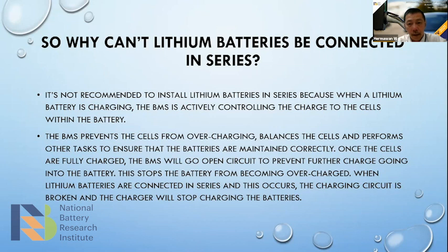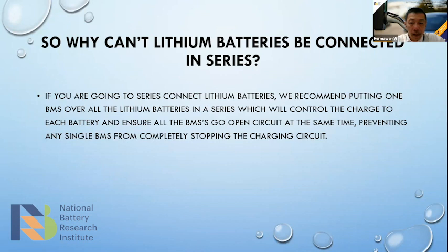That's something to consider when connecting in series or the pack, we say the pack battery. If you still need to do the series, you need to give a special BMS with a master BMS that can control every cell in the series battery pack.